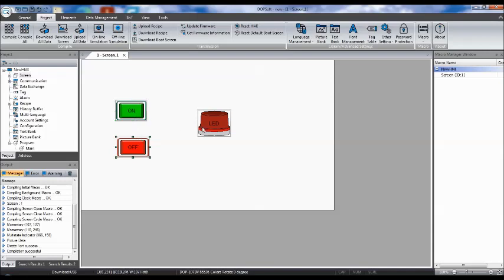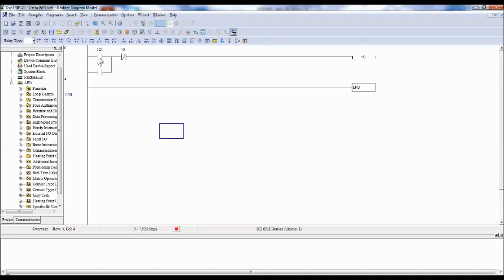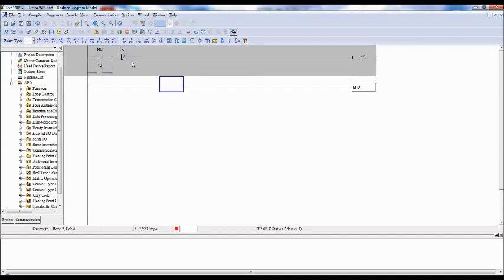So what I'll do is go to the PLC program. Now I want to control entirely through the touch screen. So in that case, go to offline mode and change the variable from X0 to M0, M0 for on and M1 for off. Now download it, download the program.